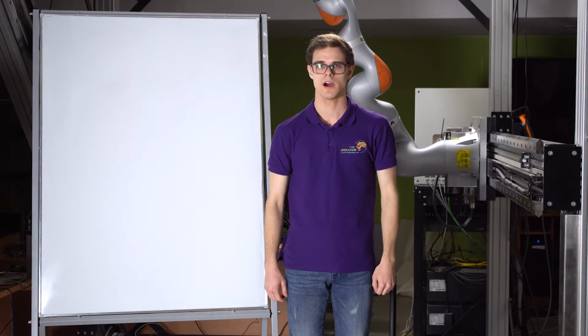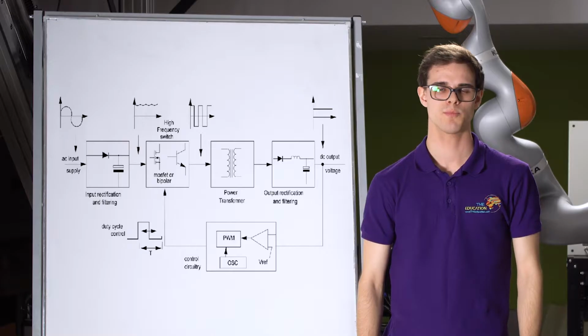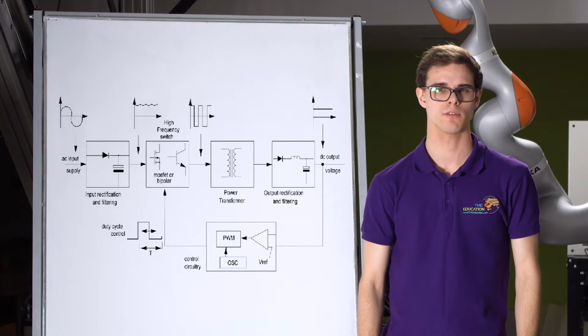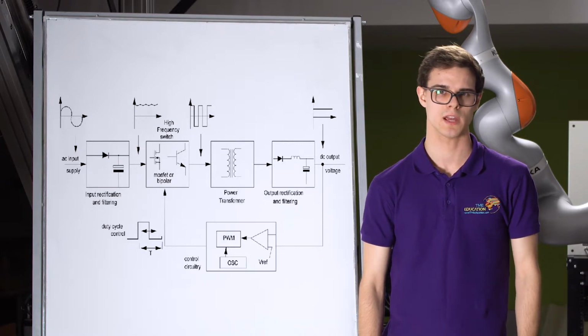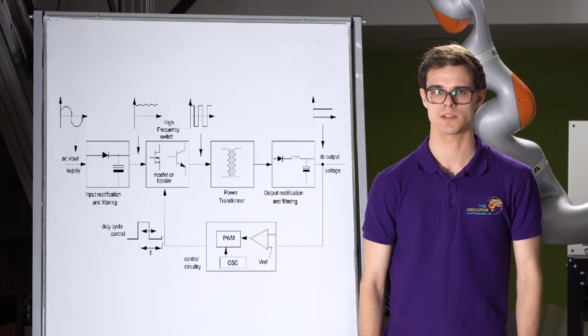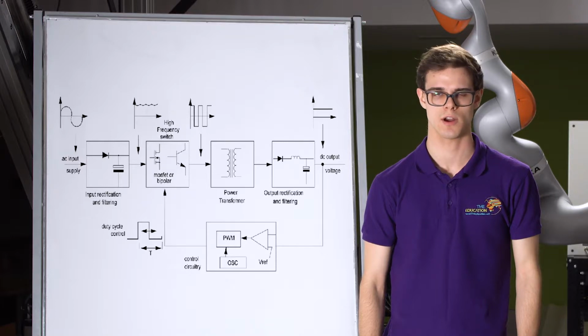The other type are switched mode power supplies, SMPS in short. The principle of operation is similar to that of linear power supplies, however, the system is more complex. Frequency of voltage changes in the power grid is relatively slow, around several dozen times per second. This forces the use of large cores in transformers. Transformers in SMPS are much smaller and they work at frequencies of around several dozen kHz.